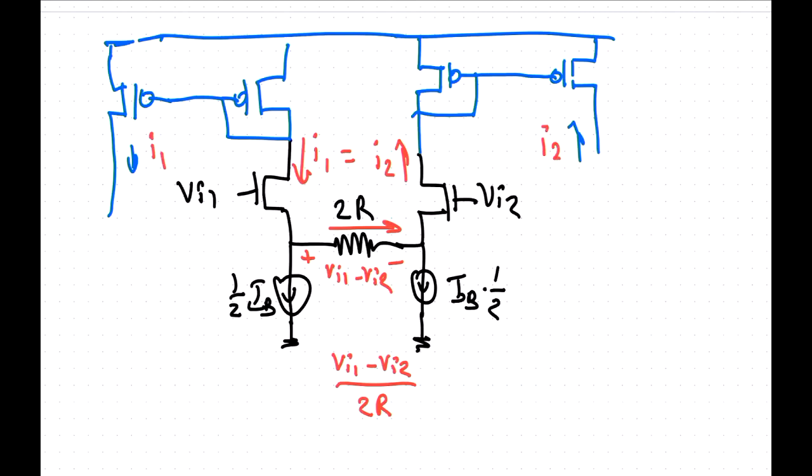And then depending on whether we want it fully differential. Actually, let me just draw a single-ended one first. Well, we don't want to have a current mirror sitting up here, between these two nodes, because then that becomes the output. And if that's the output node, then the output node is restricted in how it swings. So we just mirror them around.